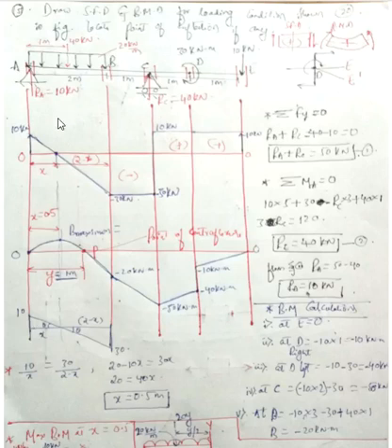Okay, Macha. Now we'll move on to the next problem based on point of contraflexure. Look at the question. He has given: draw SFD and BMD for the loading condition shown in the figure and locate the point of inflection, which is also called the point of contraflexure, if any. He has given the diagram wherein it is a simply supported beam, more of an overhanging beam.